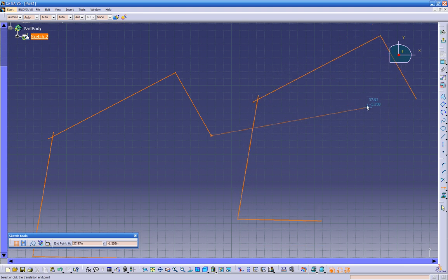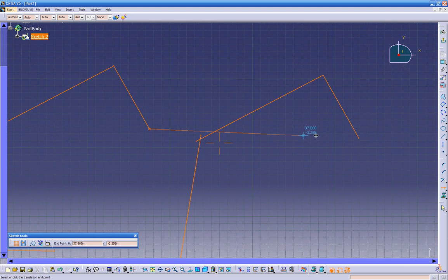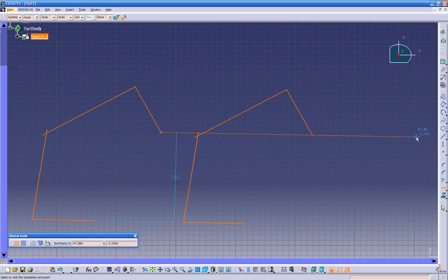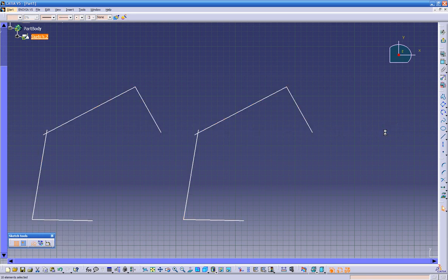While you move the part up and down, once you bring on the vertical dimension, automatically it's going to snap 10 inches apart. So right now, if you want to give it a double check, we can click on the constraint. We can click on this point with this point, and there's our 10 inches.